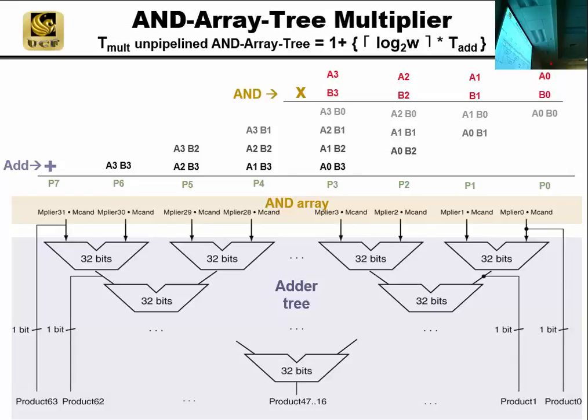Well, I can put an AND gate for this, an AND gate for this, an AND gate for this. You need 16. You can do anything in between, actually. In one clock cycle, you can have 4 AND gates and do the first partial product at the first time. Then the next clock cycle, you can compute the next row, and then the next row, or you can do this. You can take A0 and B0, and let's replace each one of these, it's actually AND, let's replace it with